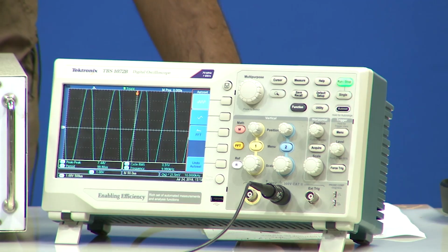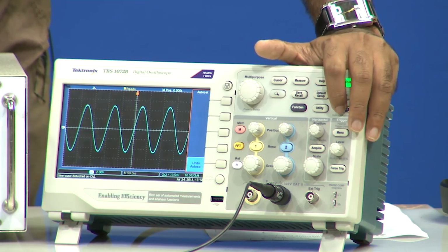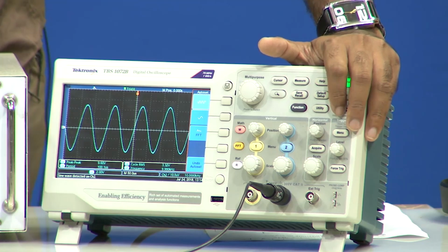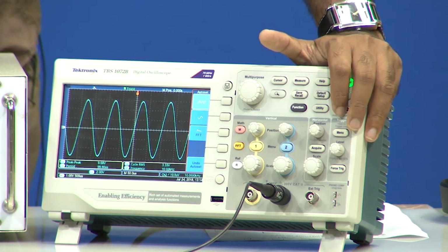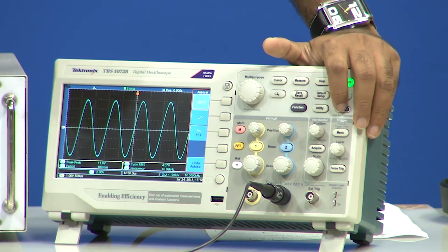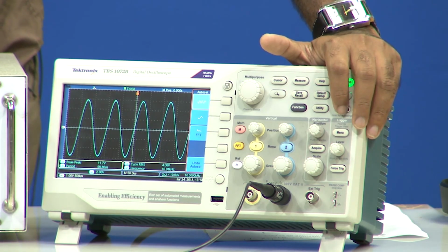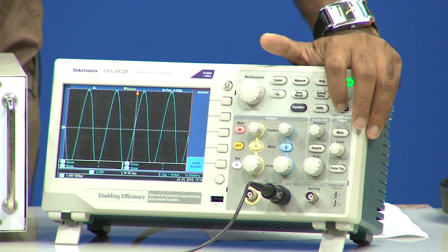Again we are making it 4.5 volt. So, for 4.5 volt, we are still getting a beautiful sinusoidal wave without much noise in it, with a peak to peak output voltage of 9.68 volt. Okay. Now, we are increasing it again, now it is 5.5 volt. So, now the output voltage is 11.7 volt. So, let me keep increasing it. So, this is 6.5, 7.5.